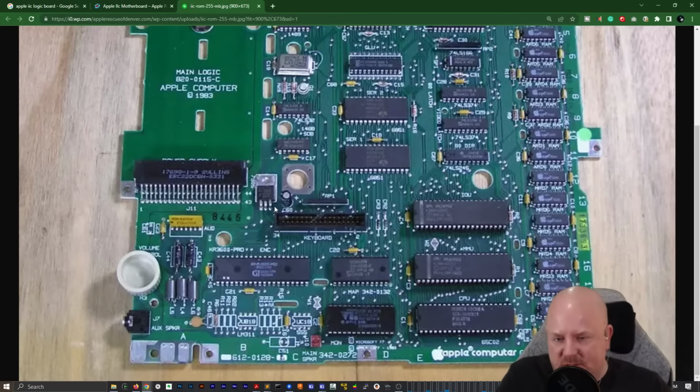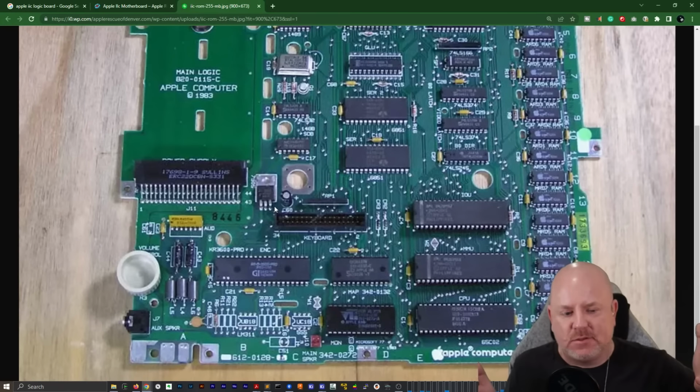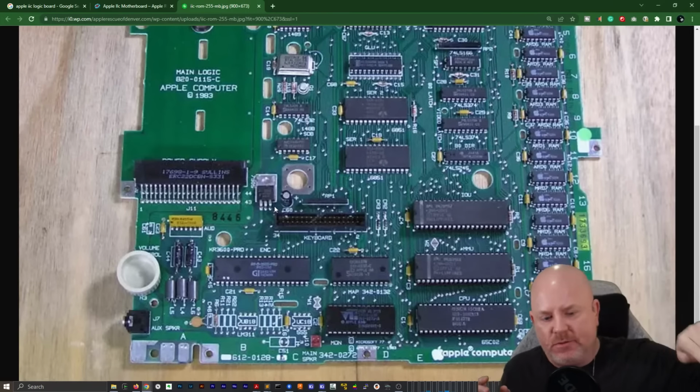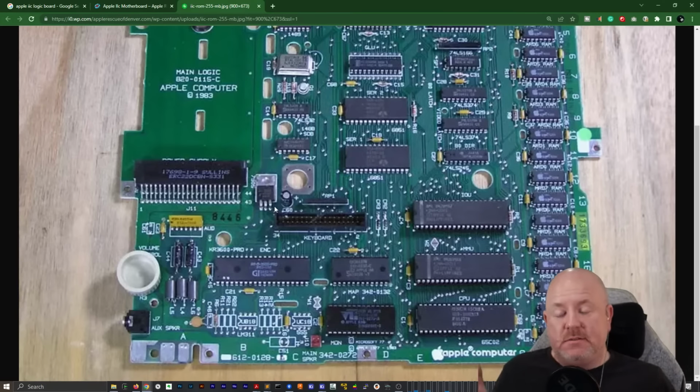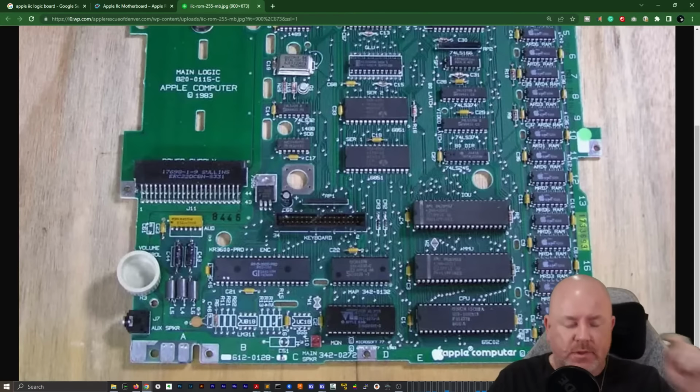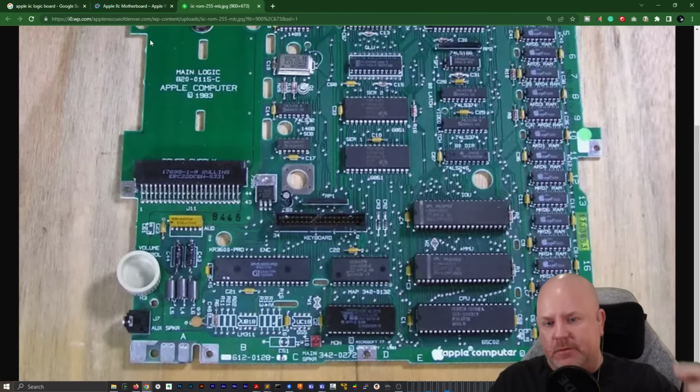That's how Apple did this. In the Macintosh LC that I took apart, they followed the same thing. Since the Apple II up into at least the Macintosh LC line, they've always arranged their boards this way with rows and columns, and then the schematic matches the row and column, which I think is really cool. Because it takes zero effort to figure out where this chip is.